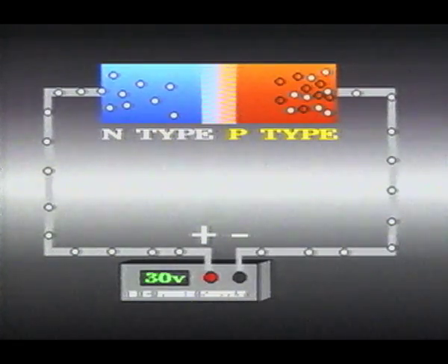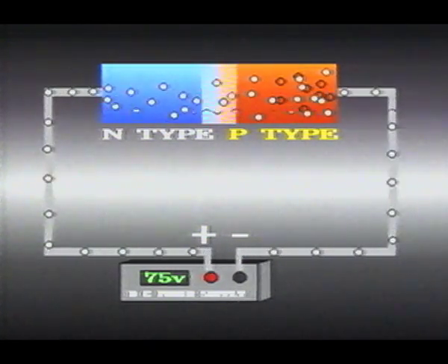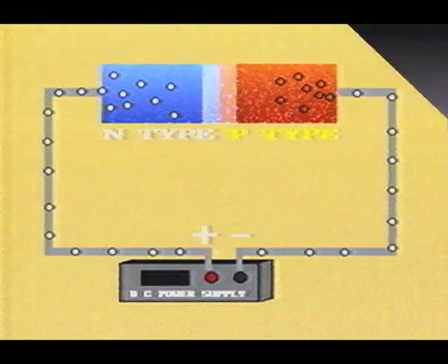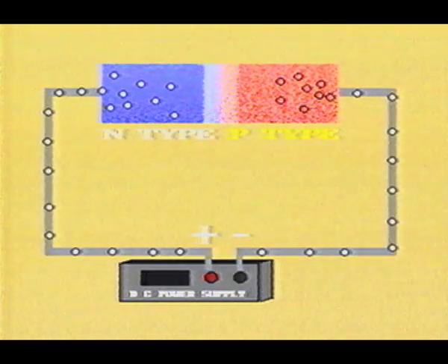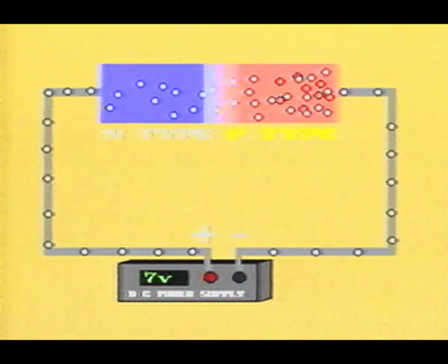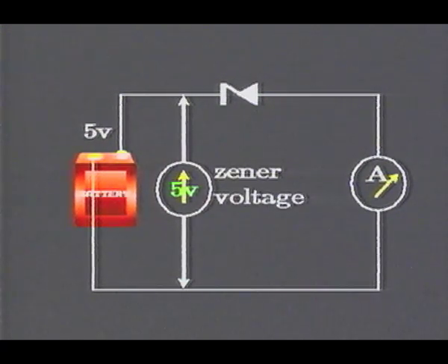You see, any diode connected in reverse bias will start conducting above a certain voltage. In regulator diodes, this voltage is regulated by adjusting its chemical composition, so that the diode starts conducting at a lower voltage determined by its chemical composition. This results in a drop of voltage across the Zener diode to the desired level called the Zener voltage.